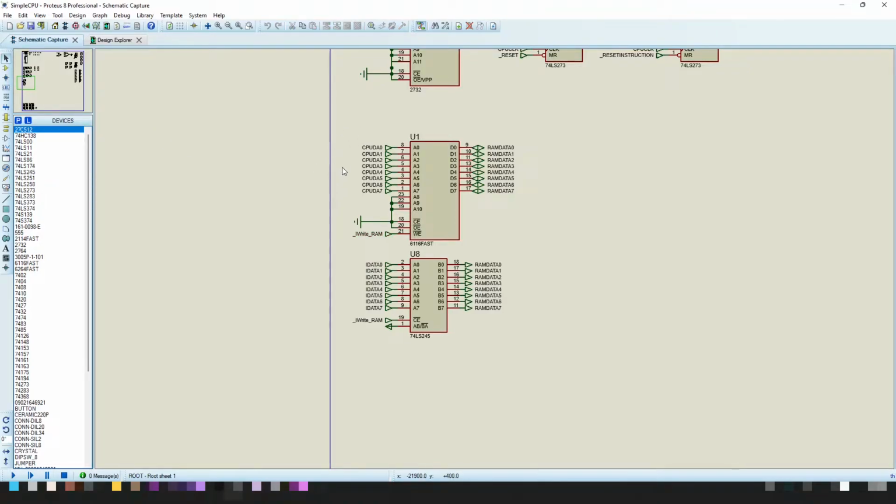Okay, this is fairly standard memory logic. What you don't want to do is alter the address being passed in while you're holding the write signal low and stuff like that. You need to make sure that you read the data sheet for how these RAMs operate to be able to get good stable operation.